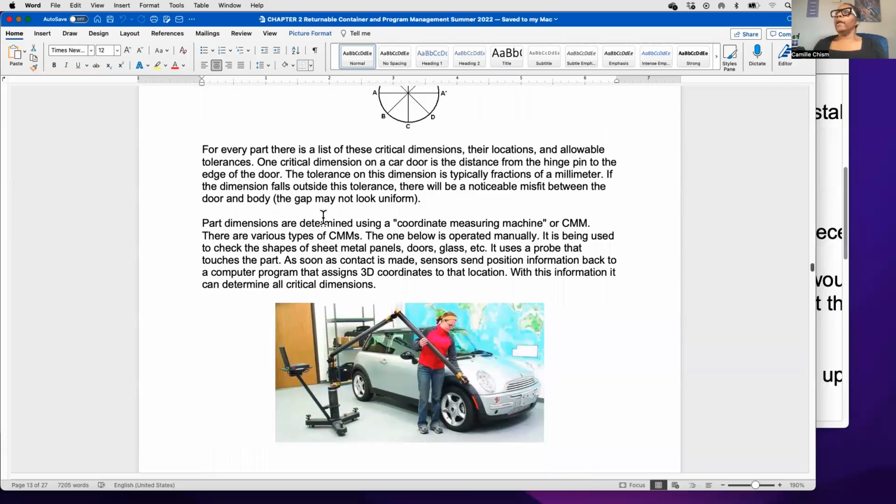So on the drawing, you are going to see the critical dimensions. One thing I've noticed with the automotive packaging, I'm sorry, not for automotive, but automotive parts. So for packaging in general, you'll see a length, width, height, and there's a plus and minus dimension for each one. But for automotive parts, many times you will only get a length and a width or a length and a depth.